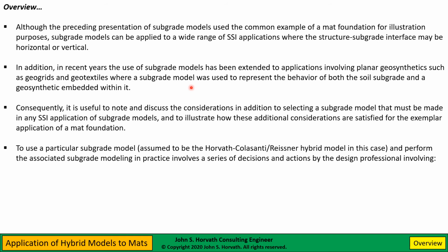So one of the things you have to look at to basically fine-tune these subgrade models for a particular application, well, you have to consider boundary conditions. Again, you have to remember that these multi-parameter models go on to infinity in horizontal or vertical directions, depending on the orientation. And you want to be able to truncate them at the edge of the structural element, just for computational sake.